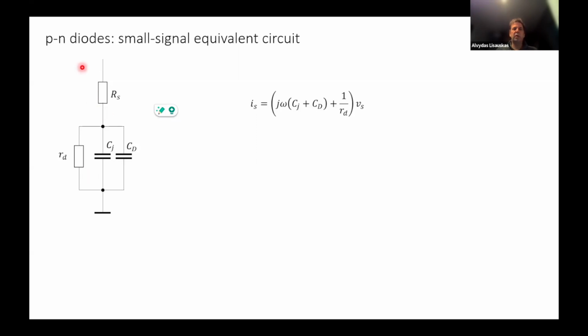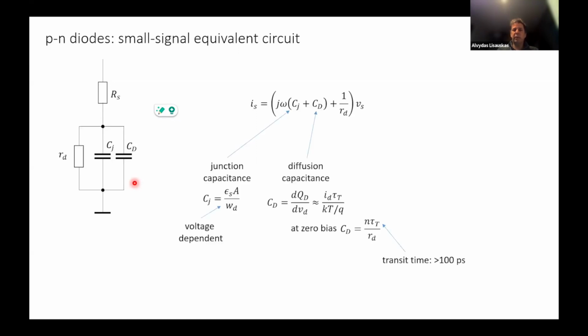And for a PN diode, a very important phenomenon is the transport of minority carriers. So there is a diffusive capacitance. The carriers must diffuse from the region where there are minority carriers. That's only diffusion transport, and therefore there is an additional term, which electrically can be very nicely comprised into this differential diffusion capacitance.